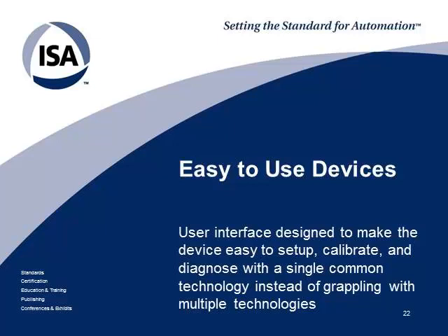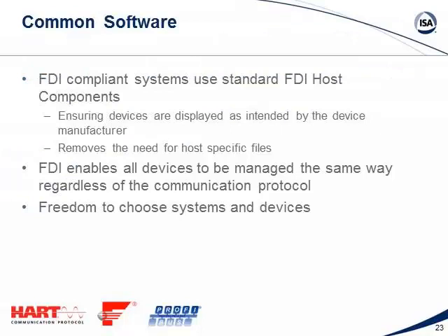what's happened over time is we had this EDDL camp being formed, and we had this FDT technology being formed, which are really two diverging, somewhat competing, somewhat complementary technologies. Obviously it's causing a hassle amongst the different suppliers and users, because in the end you see double investment, people spending twice as much money on really trying to do the same thing. And so FDI is this work where we try to take the best of both worlds and create a single device integration technology using some of those features of EDDL and FDT technology in a single integration package.